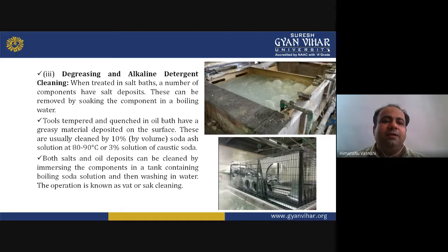Then there is degreasing and alkaline detergent cleaning. When treated in a salt bath, a number of components have salt deposits. These can be removed by soaking the components in boiling water. The tools tempered and quenched in oil have a greasy material deposit on the surface.